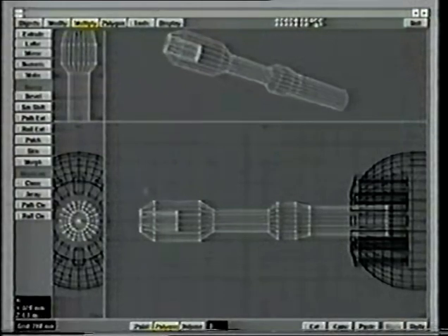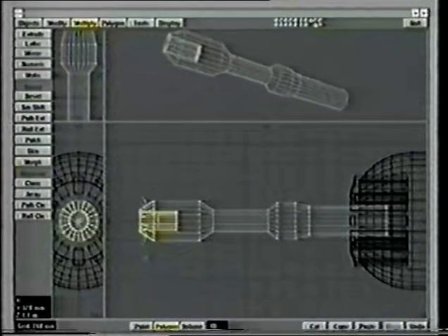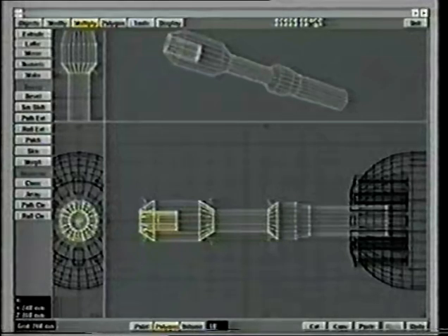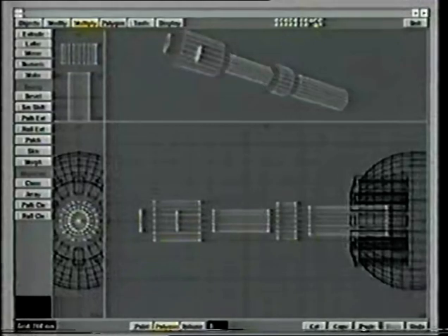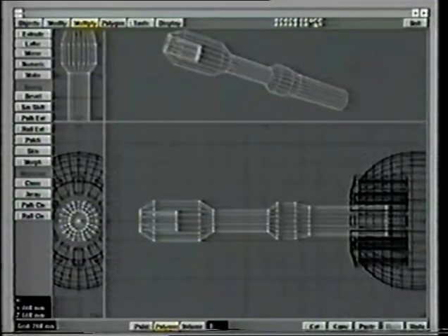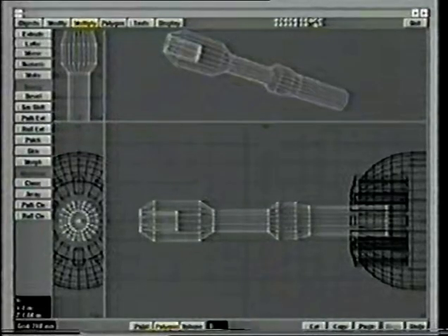So what I'm going to do here is go through and select these polygons here. Don't forget that there is a front face here, so these are separated by one set of polygons. Continue going, selecting every other batch of polygons so that you can cut them apart. So I cut that and then paste it back in again. Now, the effect that this has is that the surfaces will shade on a hard edge at the areas where I cut them away, yet they will still smoothly shade around the circumference. So, we have our gun.